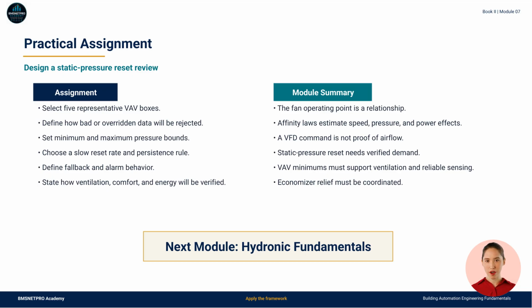Then explain how you will verify ventilation, comfort, fan energy, reheat impact, noise, and stability. The core lesson is this: fan systems should be controlled from verified relationships, not isolated points. In the next module, we move from air systems to hydronic fundamentals.